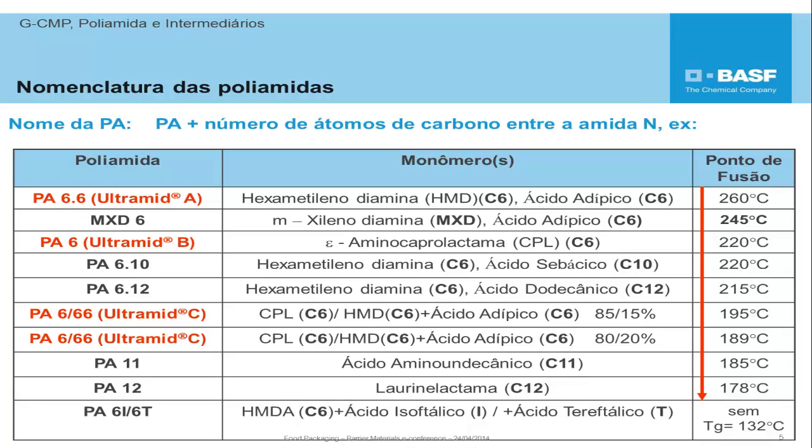Then we can notice that in accordance with the characteristic of that material is going to get a feature of crystallinity, subject that we are going to talk later, noticing as well that the composition directly affects the melting point. So, we see that in the polyamide 6.6 the melting point is in the strip of 260 degrees and polyamide 6 in the strip of 220 degrees Celsius.